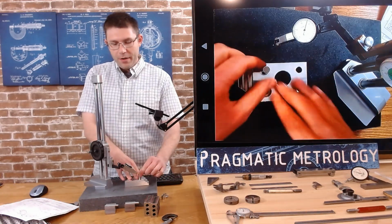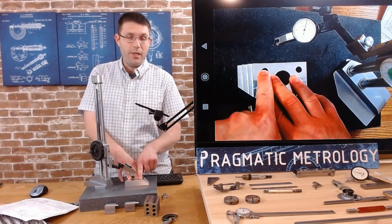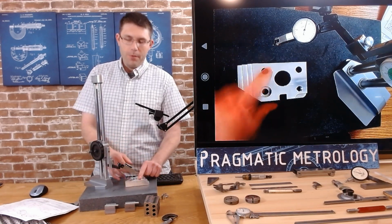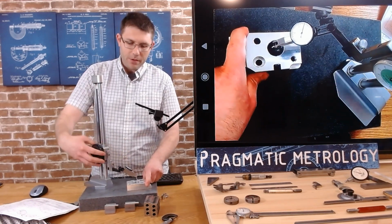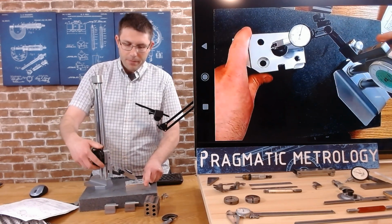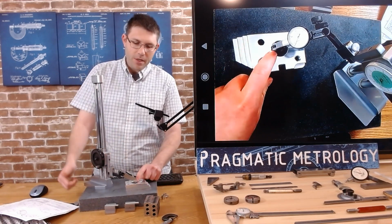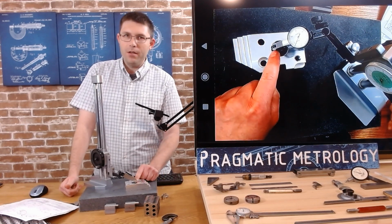If you can run the indicator directly in the hole, that should also tell you how straight the hole is. That can be hard with a very small hole like this one, but with a larger hole, you might be able to get it in there. If you wanted to do the true position of a larger hole, you might be able to get it in there, but you're going to run into the body of the indicator on the top surface.